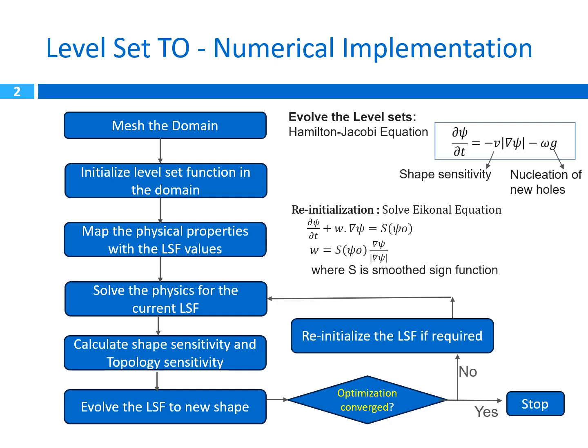This loop has to be continued till you get the converged shape and you find no difference in the objective value. While executing this loop, maybe for every 5 or 6 loops, you can reinitialize the level set functions. That will bring back the gradient to 1 and ensure you have crisp material boundaries during the level set evolutions.